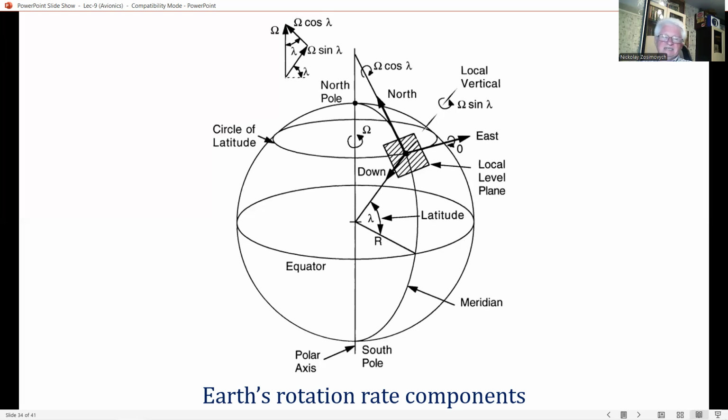It will be shown that a heading accuracy of 0.1 degrees, however, requires the gyro bias uncertainty to be less than 0.01 degree per hour. The technique is therefore not suitable for AHRS using lower accuracy gyros. And finally, Earth's magnetic field. This enables a heading reference to generally within 0.7 degrees accuracy to be established at latitudes below 60 degrees north or south of the equator.